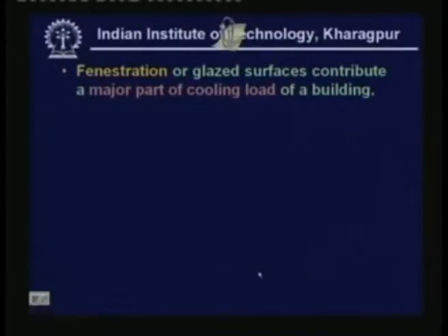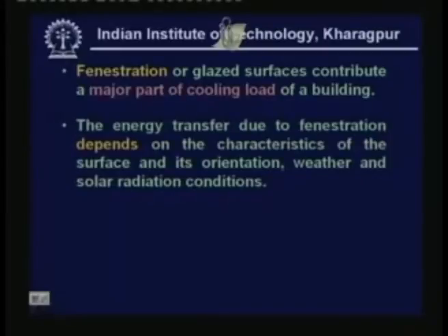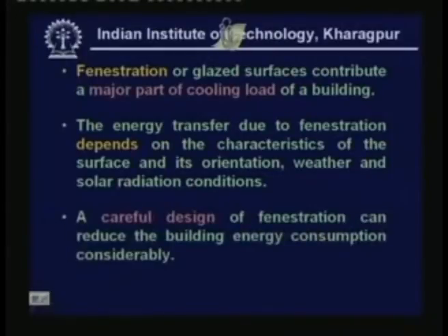Now, what is the importance of fenestration on glazed surfaces? Why do we have to consider this seriously? Fenestration or glazed surfaces contribute a major part of the cooling load of a building. The energy transfer due to fenestration depends on the characteristics of the surface and its orientation, weather and solar radiation conditions. So, careful design of fenestration can reduce the building energy consumption considerably.